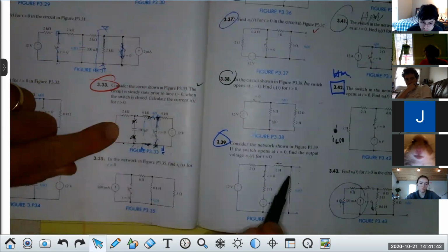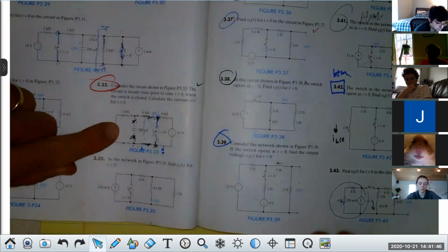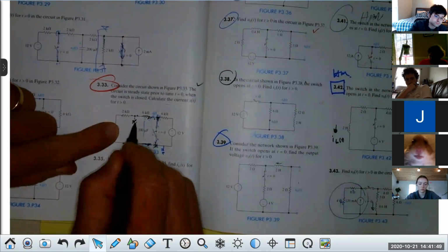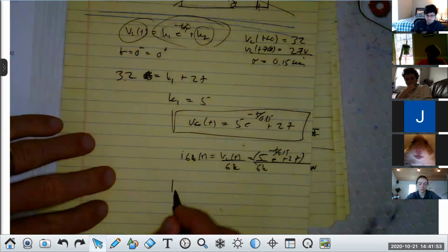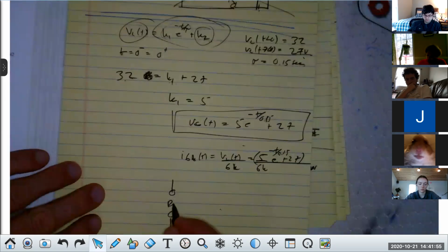Yes. That's the reason. So we're shorting the capacitor there? No. We remove it. You literally rip it out of the circuit. This is what's left. It would look like, here's where the capacitor was. There's where I want our Thevenin.